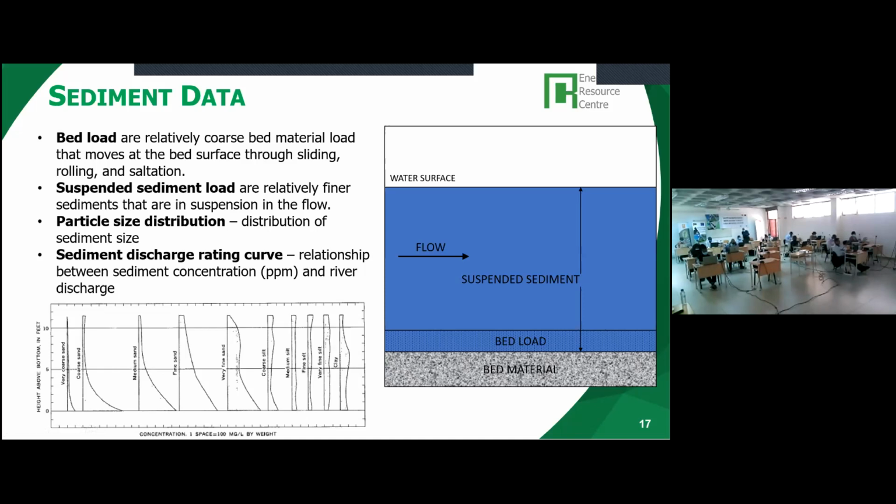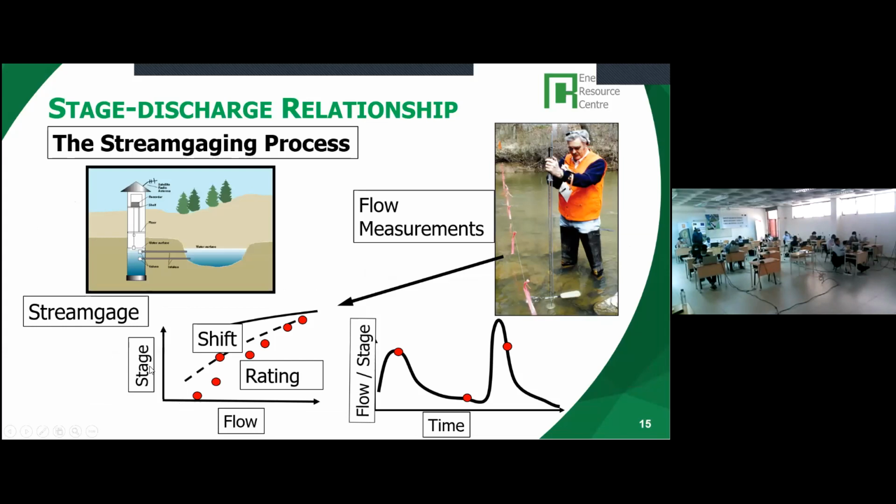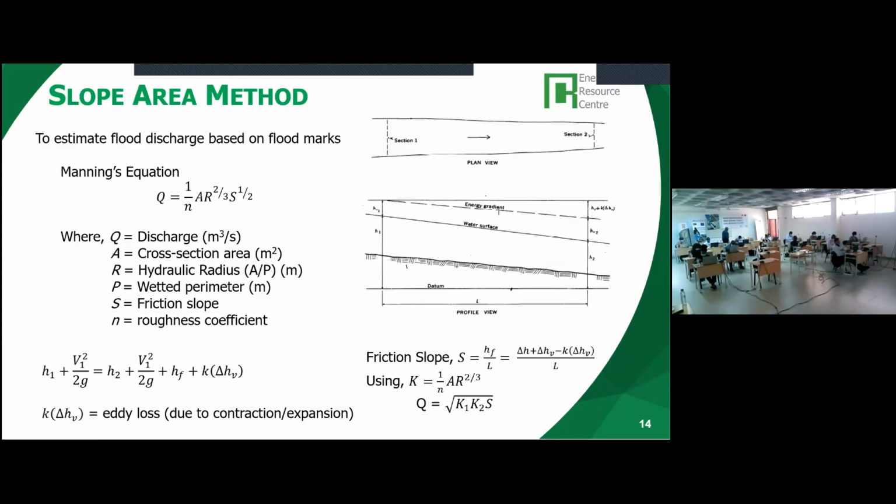We talk about the possibility of choosing 95% of the duration, and if we could choose two-stage, 95% and something about 6% of the flow duration curve, taking into account the efficiency of the turbines, for example, Kaplan turbines.